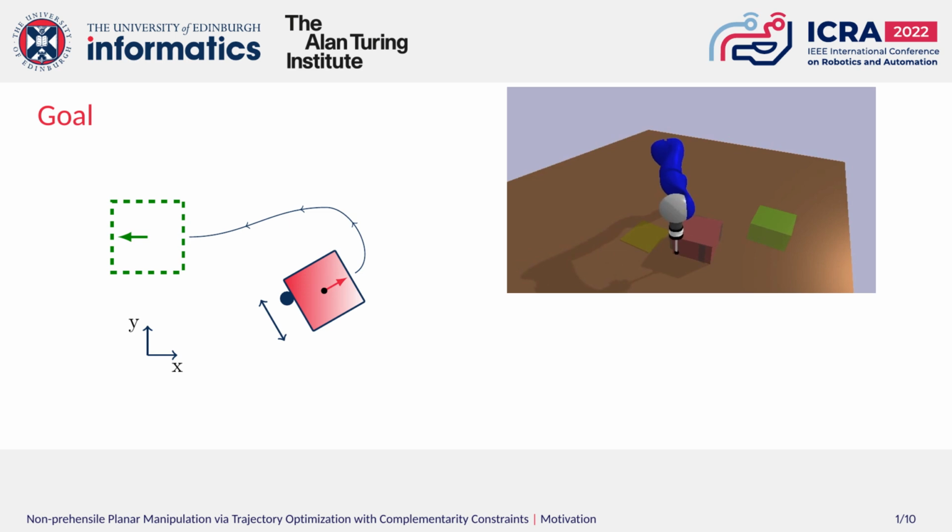However, as you can see, the real object in red significantly deviates from the planned trajectory in gray. Note as well that in this example, the sliding motion between the robot and the box occurs in spite of the planning enforcing a sticking contact between them. This happens due to the non-prehensile nature of the task. In the absence of a full grasp of the object, any mismatch between the prediction model used for planning and the physical environment will lead to deviations of the desired motion.